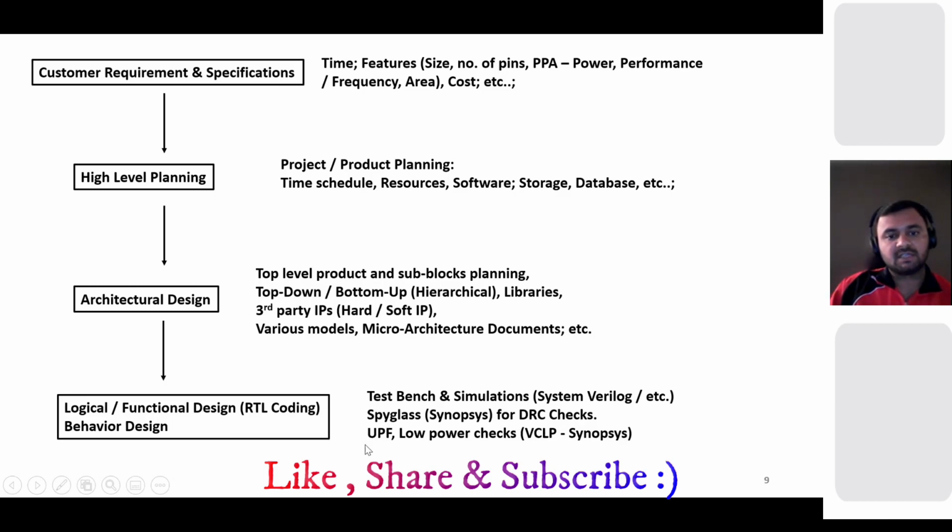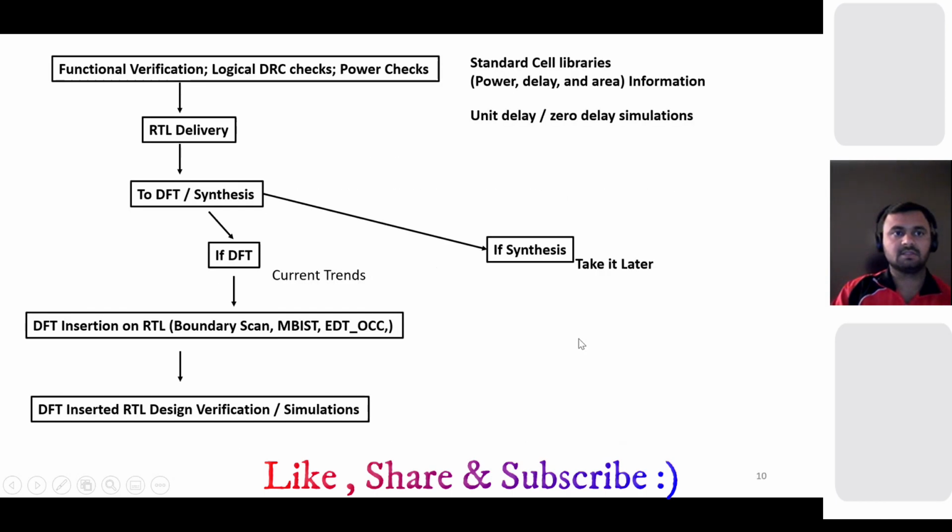You use UPF here. If your chip is low power and you are doing low power designing, then you use the Unified Power Format here. It's an IEEE standard. And you do the low power checks, which is called VCLP, and it is also supported by Synopsys. Okay, so you understand how, after customer requirements, it goes to the logical and functional level.